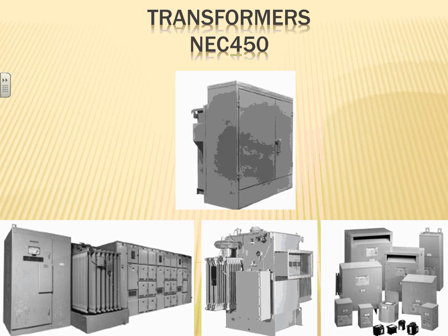So the nice thing about these is, like we did Ganda, I was part of an engineer that worked in Ganda building and Mayo Clinic. What they do is they have their 13.8 distribution system in the basement, and then they take a 13,800 volt feeder from the first floor all the way to the 13th floor, and up there they have a substation like this that takes a 13.8 fuse disconnect on this side, and that tied to a transformer that transforms it down to a level of 480/277. That's one substation we did.